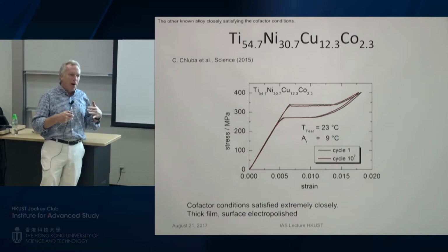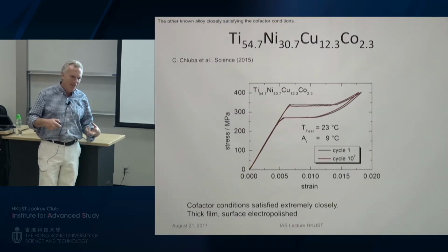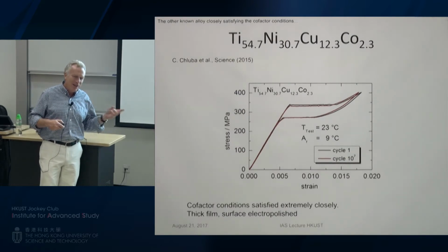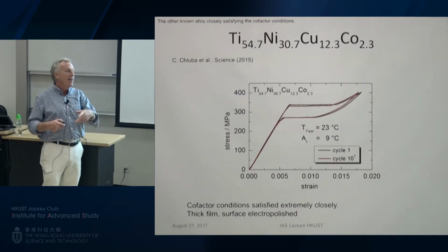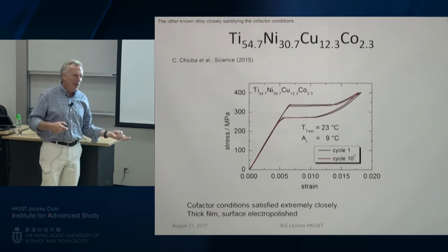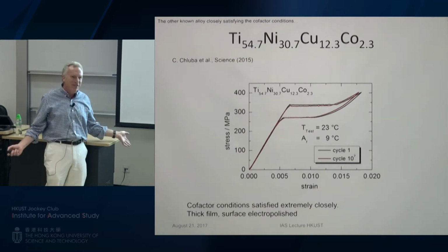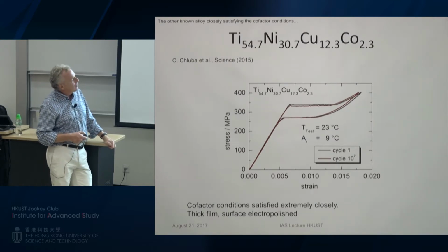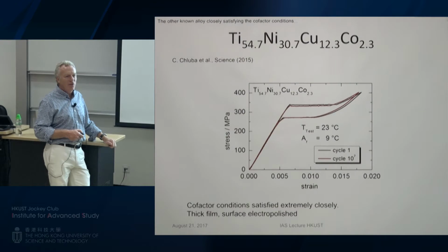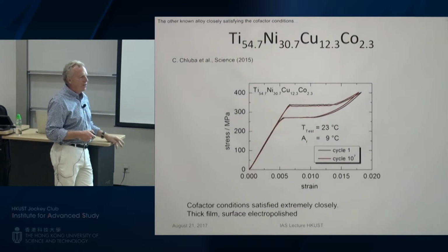Part of that can be that stress does not change the lattice parameters that much. So if you satisfy cofactor conditions under 0 stress, you could approximately be satisfying them under stress. But of course, as soon as you stress something, cubic is no longer cubic. Tetragonal, or in this case orthorhombic, is no longer orthorhombic. Everything is triclinic. Everything is inhomogeneous. Nevertheless, the strains are small perturbations, so that could be relevant. But the differences we don't understand.